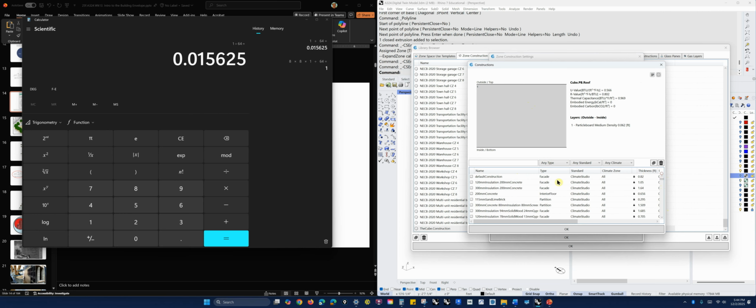What you want to do is go to default construction, so just scroll to the top. If you select that, you'll see that it's just concrete. The reason I'm choosing that is because it's a construction that has just a single layer, but you can actually pick any of these because you can then completely adjust it. So pick a template and again copy it. Over here you copy it, and when you do that, you'll be able to name it.